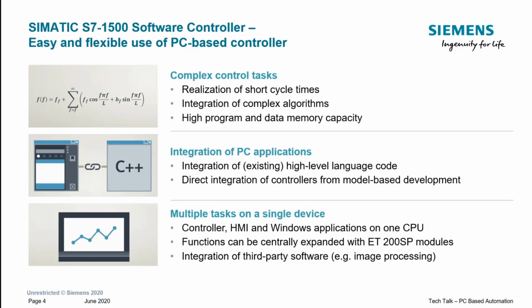Now, the integration of the PC applications is obviously where these software controllers sort of stand apart. If you're already in a situation where you have an in-house application developed in, say, C++, C#, VB, and you need to integrate it into an S7 controller, you can now use the development kit to do this natively. So the app that you've already developed in-house, you can run it on the Windows side of these devices, and you can have comms straight in. Imagine a small conduit straight into that S7 controller to pipe data backwards and forwards in next to real time.